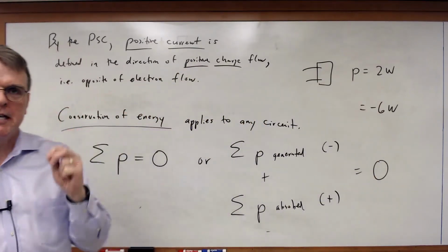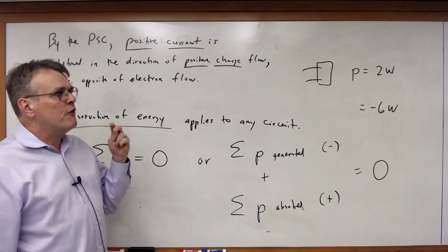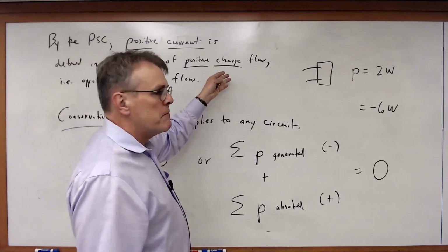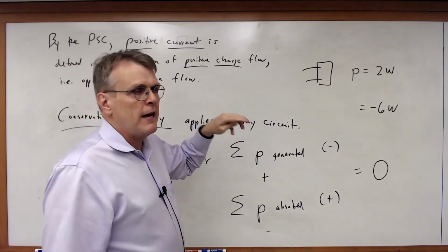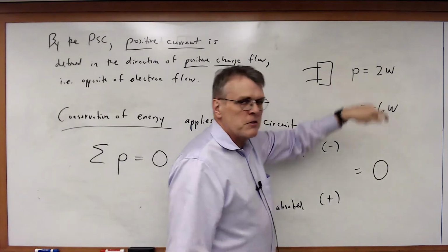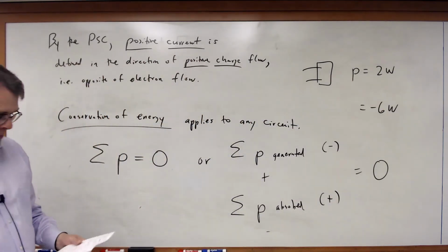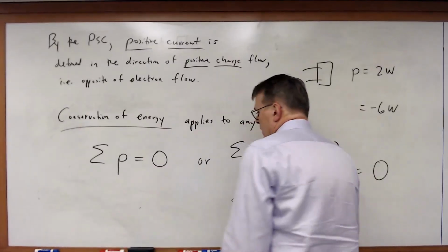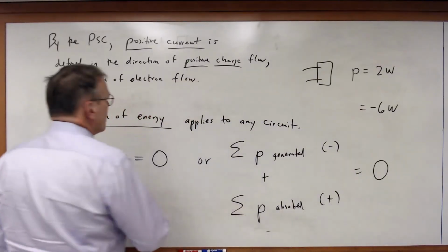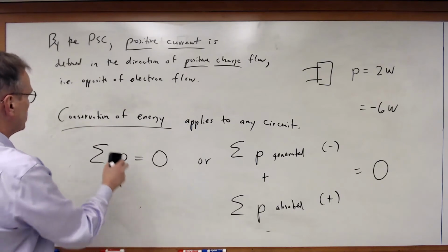So just think about that. I don't need any other kind of definition of absorbed or generated. No word added on. Just that number and the sign. And that describes exactly what the power of the element is. So let's just work a couple of quick examples to see how the passive sign convention works to finish this up.